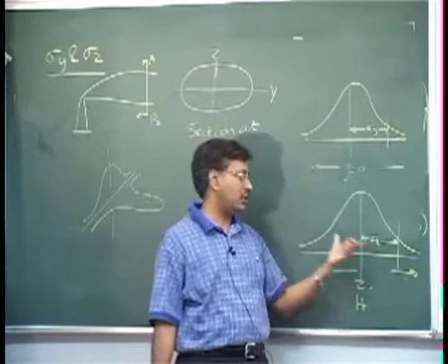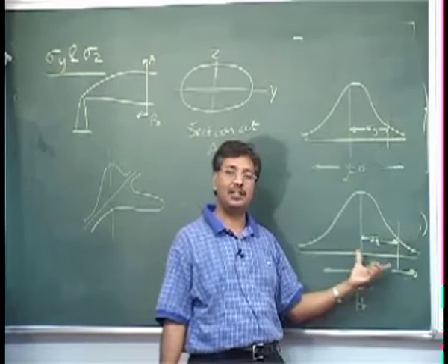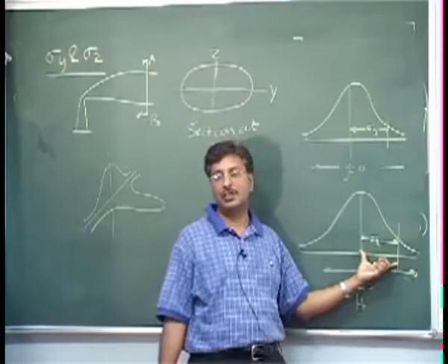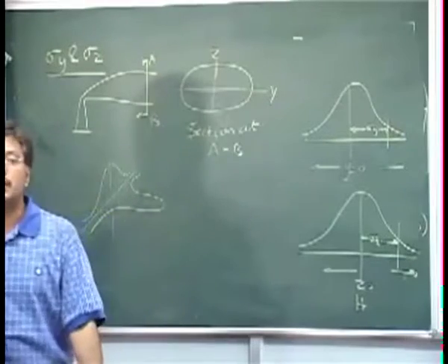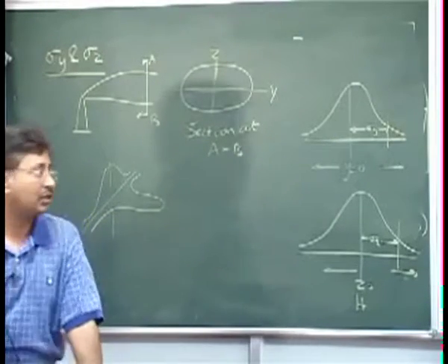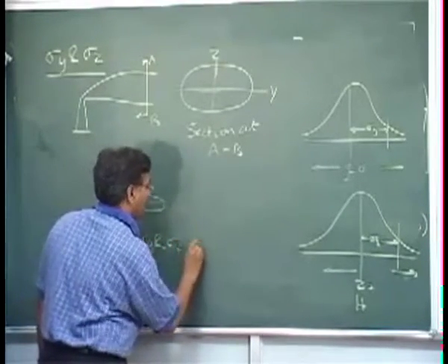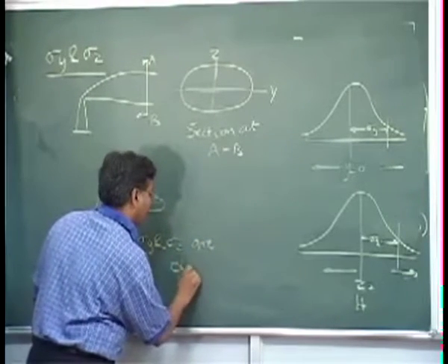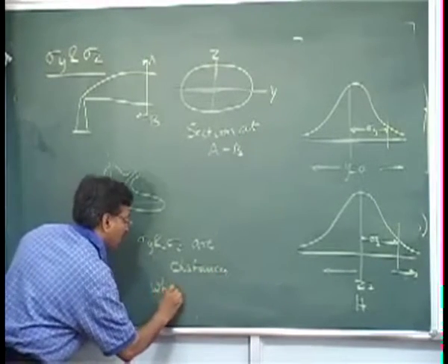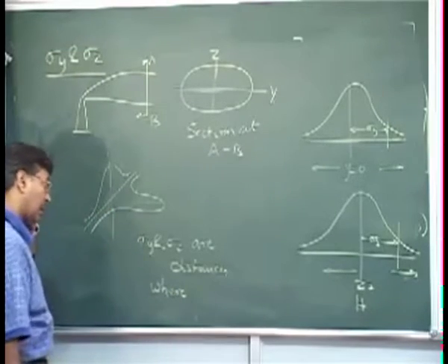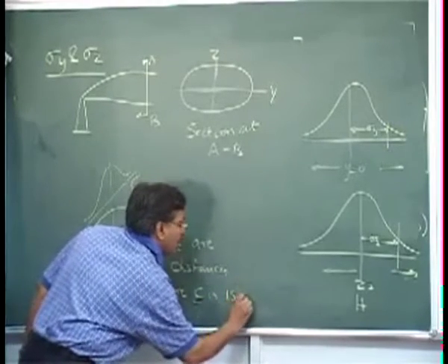The distance where the concentration equals 1 sigma z is called sigma z. Remember that sigma y and sigma z are not concentrations, but distances where the concentration is 1 standard deviation.